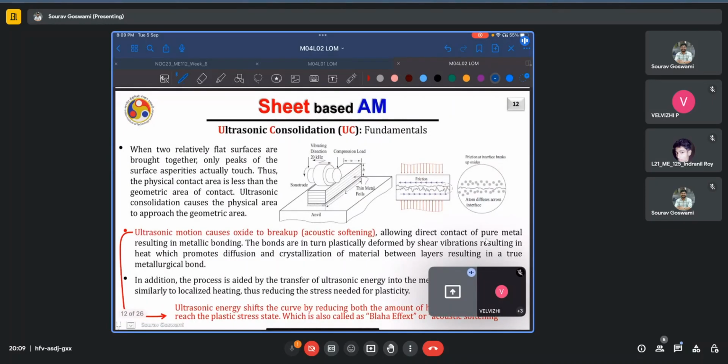So this is the surface that I was talking about, and we can see the asperities here. We see how the surfaces are never perfectly flat. They always have these asperities on them, and thus the actual area of contact is only a very small fraction of the geometric area. One would assume that this entire geometric area, and also in the other dimension, is in contact.